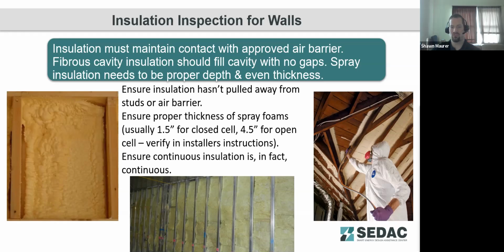But your code official is going to go through and try to sample and make sure that you've got the properly installed insulation. You don't have areas that are too thin, or where you've got discontinuities in the insulation. Especially if you are required to have continuous insulation, they don't want to see gaps or areas of missing insulation.